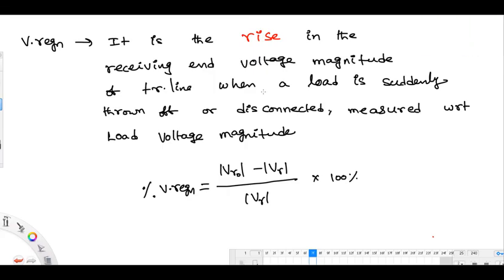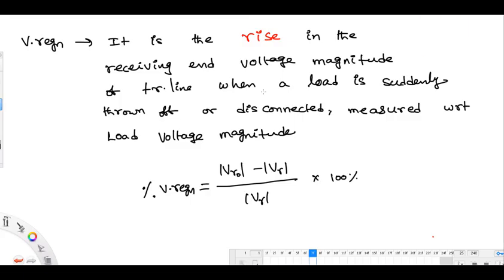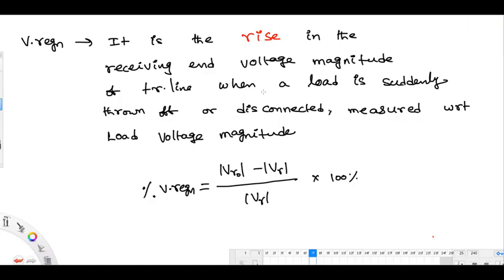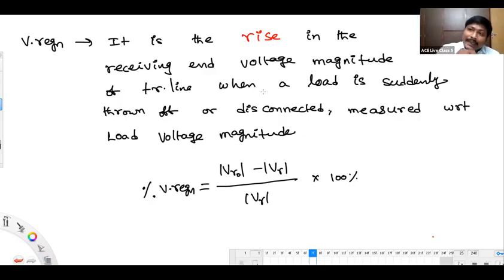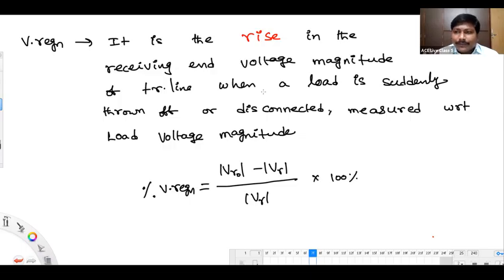We are forcing the people to use the distributed model for transient analysis. But in actual practice, it is lumped. If they feel it is more difficult to use because of capacitor switching, circuit breaker switching, all these things. If you take that line as a long line again, then the whole analysis will become more laborious. But in some conditions they might have converted and done it.